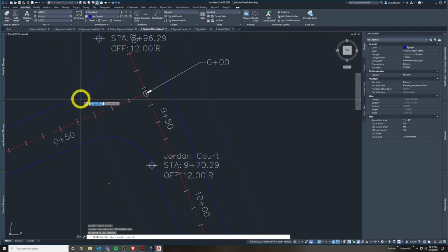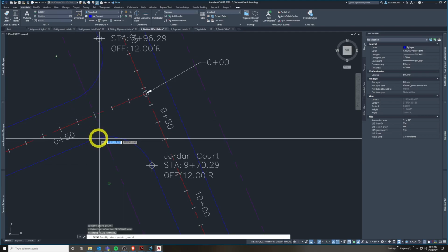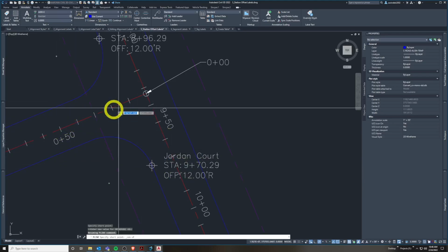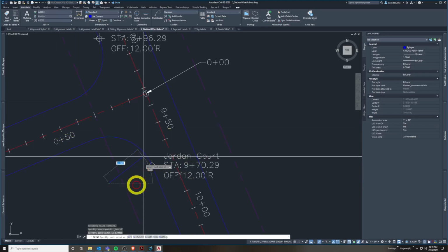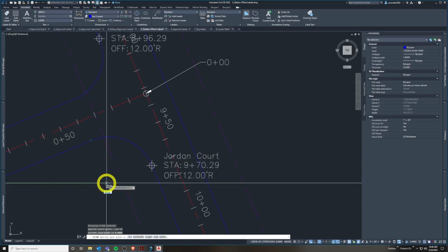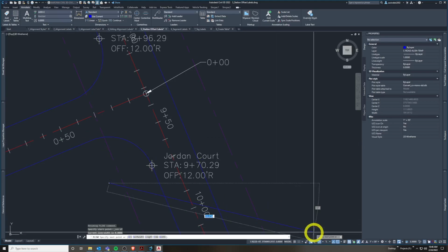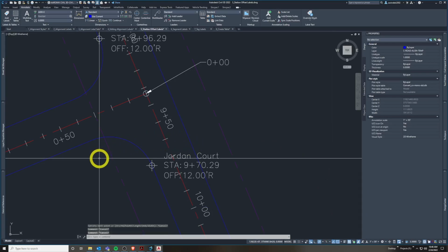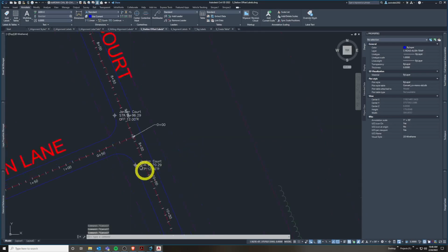And now I hover here, it's only going to center, see? No other snaps, midpoints or endpoints or nodes. That's really helpful. I draw this polyline, but now that command's over. It's now going to all my running snaps again, which are turned on here. So that's a little confusing, but object snaps are critical to learn if you want to get good at AutoCAD.